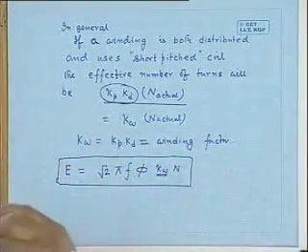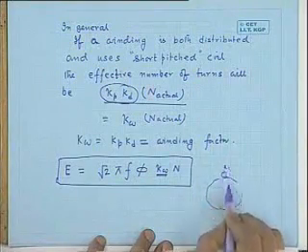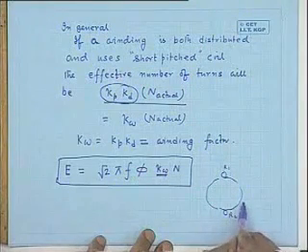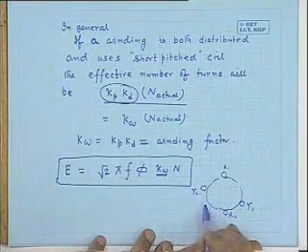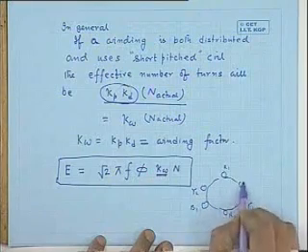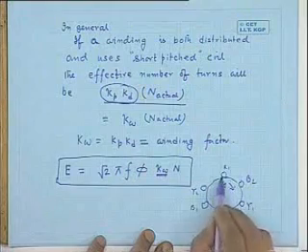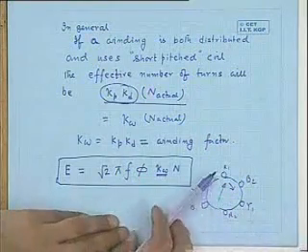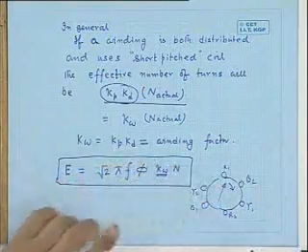Now, so far, I will point out here a simple distributed coil, a three-phase distributed coil. Let us go to that winding. You just go through that. I will not draw, but I will tell you one thing. Say two-pole configuration. This was R1, R2 I placed like this. Then Y1, Y2 I placed like this, and B1, B2 were placed like this. Suppose there is a magnetic field moving relative to these coils, then there will be induced voltage in R1, R2.